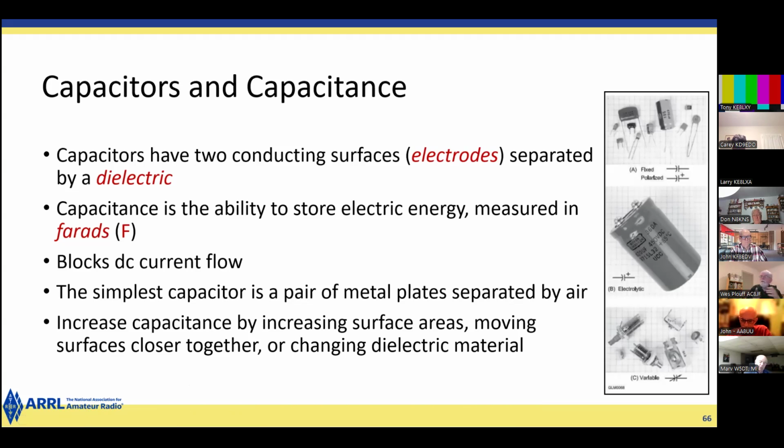that are connected to alternate terminals. So you'll have positive, negative, positive, negative, positive, negative. The idea is you get more capacitance by placing the electrodes as close together as possible, but not so close together that they arc over or touch each other and start conducting.